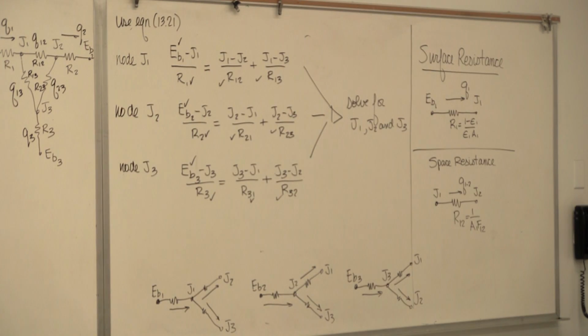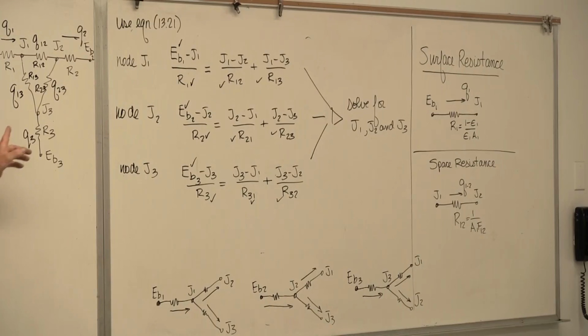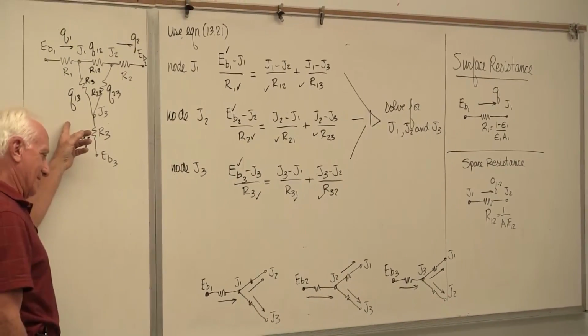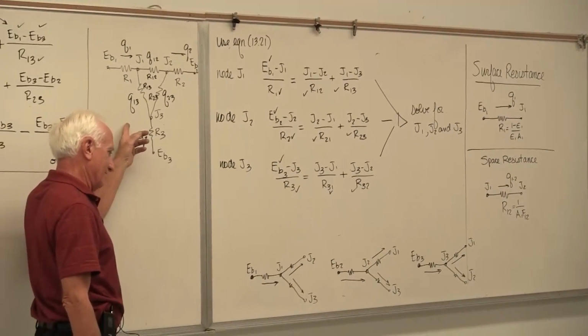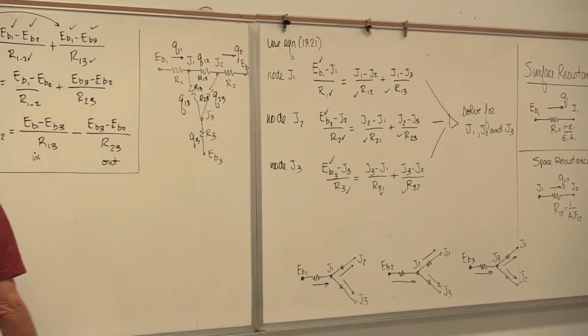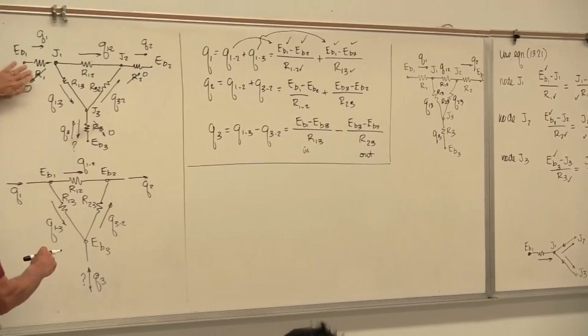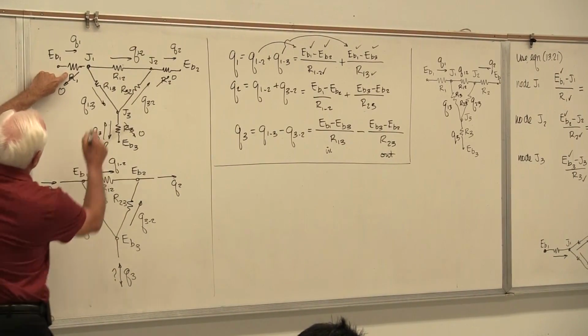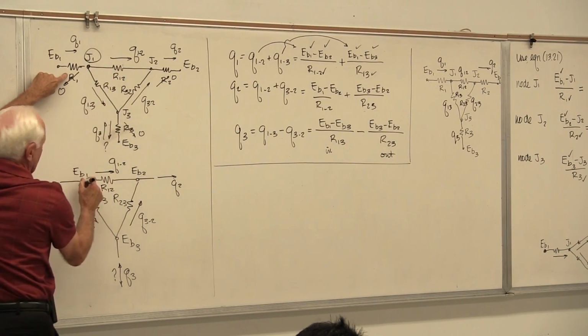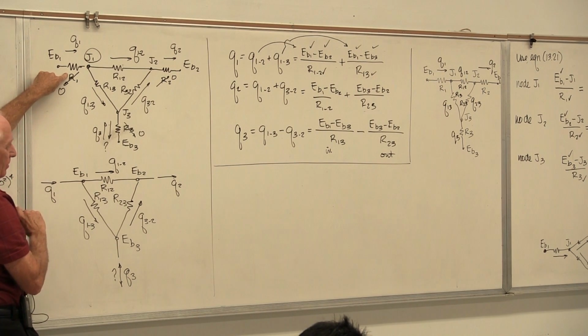Okay, so the easy one, all the surfaces are black. Look at the picture. By the way, just so you know, are there any J's? No, there's no J's. When they're not black, are there J's? Oh yes, there'll be the J's now, the radiosities. They're the unknowns. Okay, over here, all black, no J's. By the way, when I got rid of that resistor, why did I replace that J1 at that node with EB1? Sometimes that confuses people.